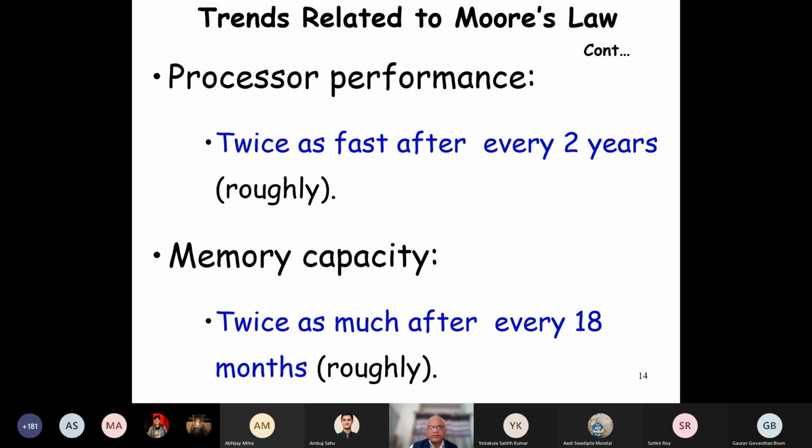That is what I was also going to answer. We'll see that memories are regular. The DRAM is a very regular structure, whereas the processor is irregular. Even though you have a lot of transistors available that you can put on the chip, you cannot really use them. So the memory improves much faster.